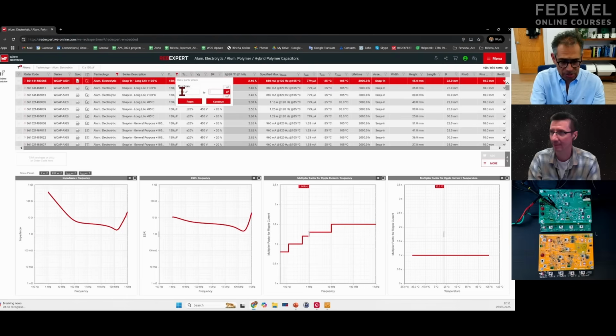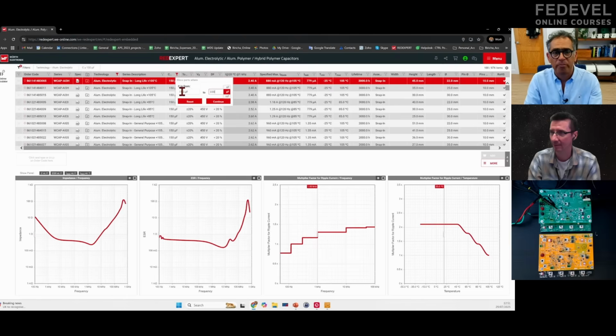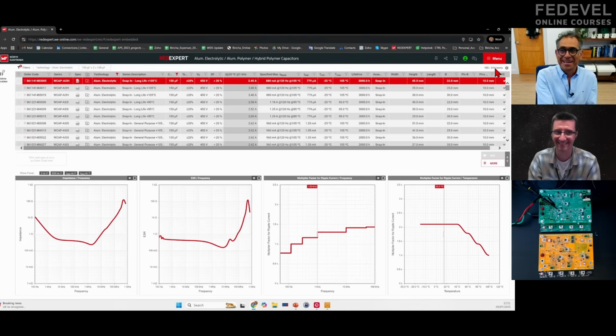Okay, then we said that the minimum amount of capacitance had to be bigger than 150 microfarad. So let me narrow down my choices and only look for from 150 microfarads to 330 microfarads. Right? And it goes down to 314. We started with 2,000 choices, and now with 300 choices.